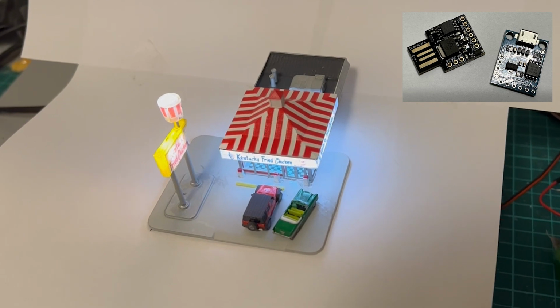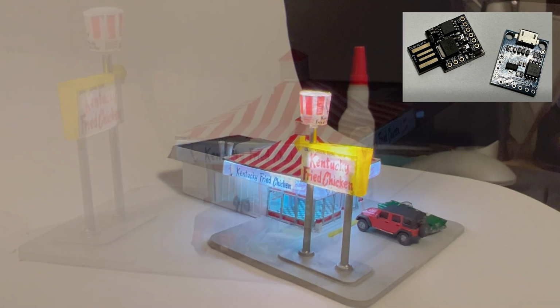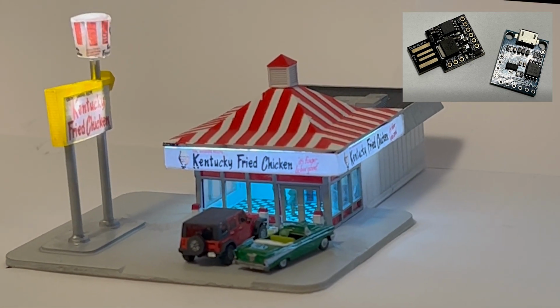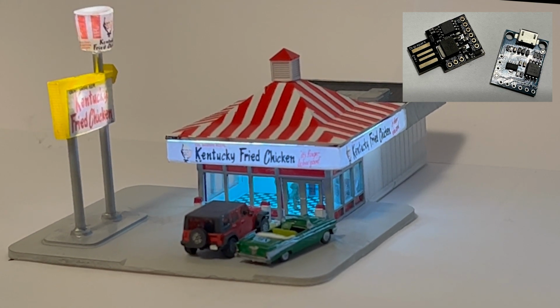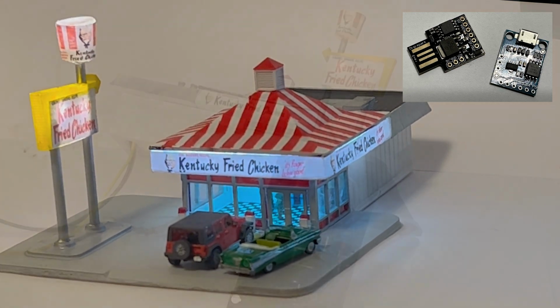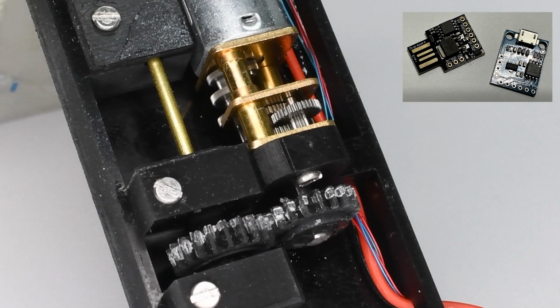To control the motor and the LEDs, I use a very small microcontroller from DigiSpark, an ATtiny85. It's smaller, and much cheaper than the more expensive Arduino Uno or Nano microcontroller I normally prefer to use. But the ATtiny85 has only 5 input and output pins, so there is a limitation to using the ATtiny85 if your project needs more pins on the microcontroller.